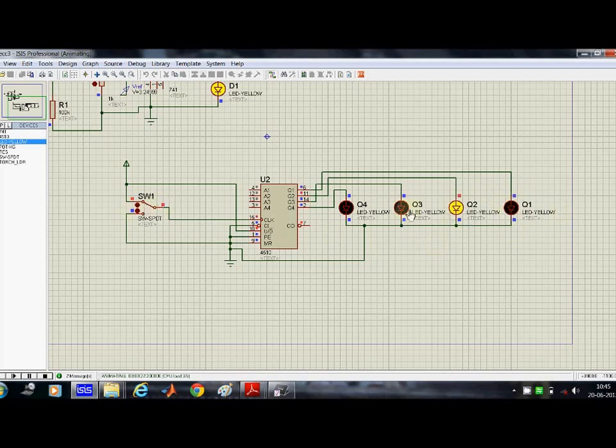You see, this is now 10. Then the binary representation, the BCD representation for 3 is 11, that is 0011. So you see, this is now convincing to all of you, I think, and this is representing 4. Now I'll be using a BCD display, that is a BCD to 7 segment display, and you will be seeing the whole numbers, from 0 to 9, displayed on that 7 segment. That 7 segment has an inbuilt decoder, from binary to 7 segment LED decoder.